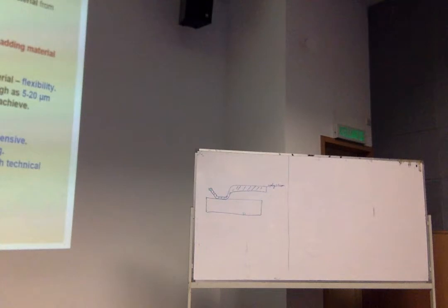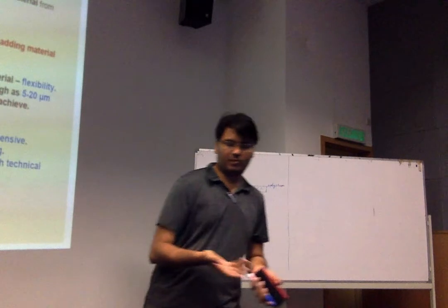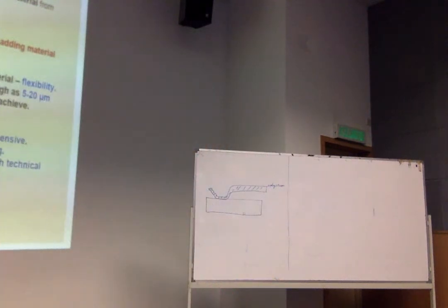So I think again I'm coming back to the same analogies. If you remember, the beach example that I used to give. If you want to make a small igloo type of thing in the sand, you keep your hand and then you fill the sand and you remove the sand. So you make the shape of an igloo or a house type of a sand castle or something like that. In that case, the hand which you used was the sacrificial layer that you later on remove to get the shape. So such sacrificial layers are required in building this surface micromachine.